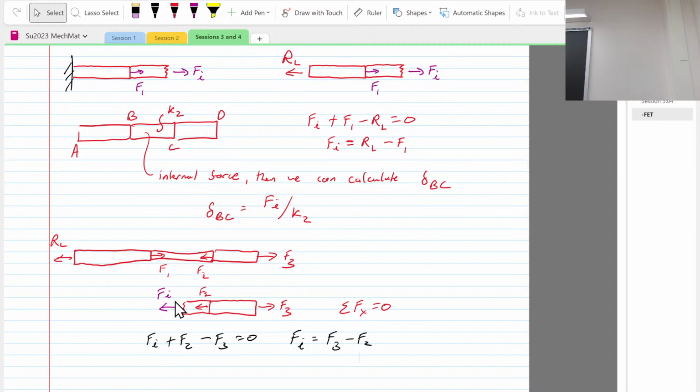Well, you combine all three of these, and there are three springs in series. Or you could do springs in series, right, and then put that in series with this, right? But if you have three in series with each other, the easiest thing to do is: 1 over k EQ for the whole system is gonna be equal to 1 over 4k1 plus 1 over 2k2 plus 1 over k1. Yeah, then that would be 5 over k1.